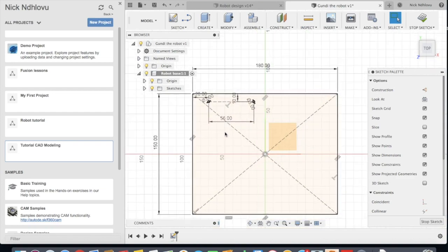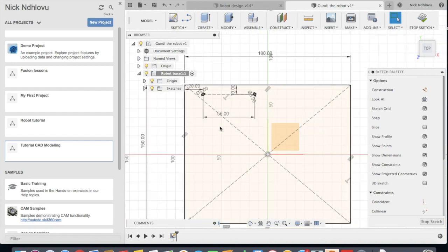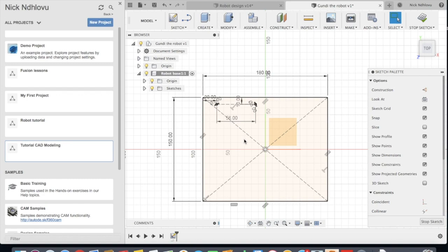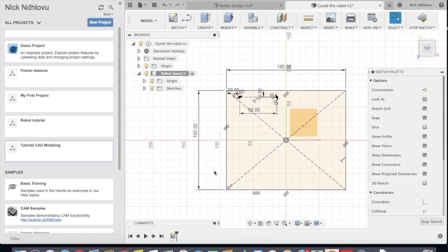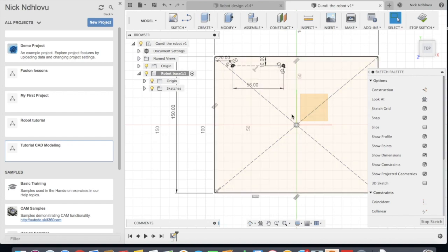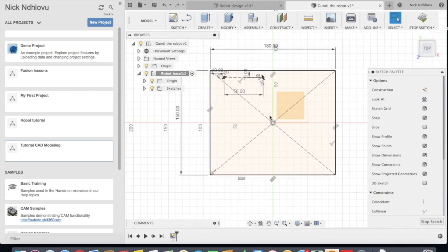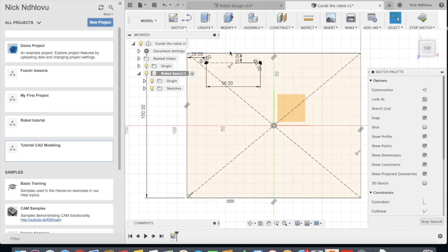Now I'm going to show you a cool feature of CAD modeling. Say, for example, we want to create these holes exactly in the same position, but on the left hand side or at the bottom side here, right? One way is to go through the long method, create a line, then create a circle and another circle here, right? So someone thought, why don't we just mirror these features? Why can't we just click a button and easily replicate these features on this side?